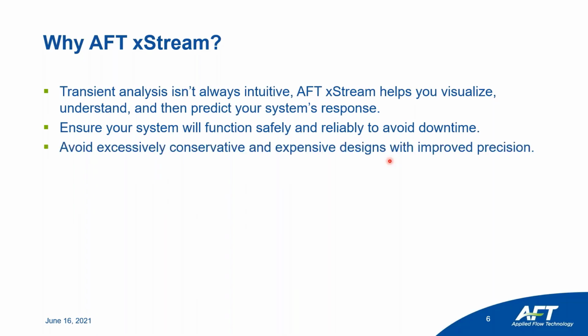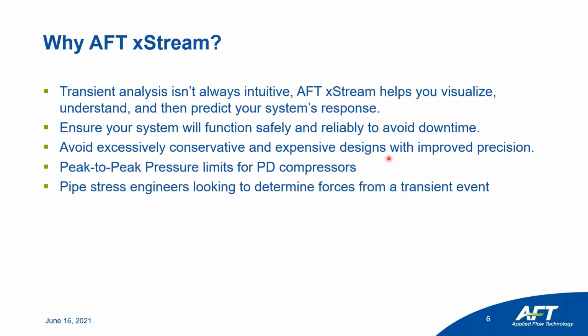It will help you avoid excessive, conservative, and expensive design with improved precision. You will be able to calculate peak-to-peak pressure limits for PD compressors. It also helps pipe stress engineers looking to determine forces from a transient event.